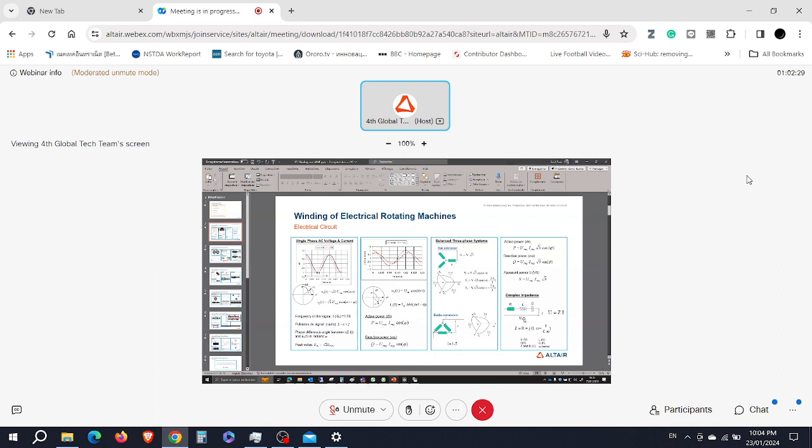When we move to complex impedance, this is something we need mainly when we deal with induction machines. So we have this complex value. The real part is the resistance, and the imaginary part is mainly inductance and capacitance. It can happen in your circuit that you have an RLC component. For the motor, we used to use an RL component, and most of the time the imaginary part is due to the inductance, and the real part is due to the resistance.